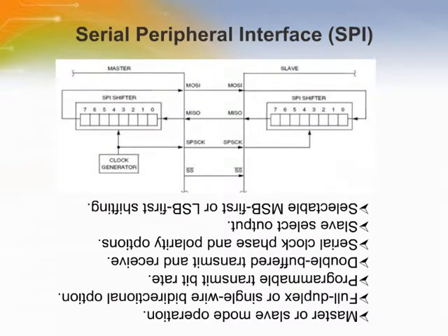The Serial Peripheral Interface, SPI, module provides for full duplex synchronous serial communication between the MCU and peripheral devices. These peripheral devices can include other microcontrollers, analog to digital converters, shift registers, sensors, memories, etc. The SPI runs at a baud rate up to the bus clock divided by 2 in master mode and up to the bus clock divided by 4 in slave mode. Software can poll the status flags, or SPI operation can be interrupt driven.